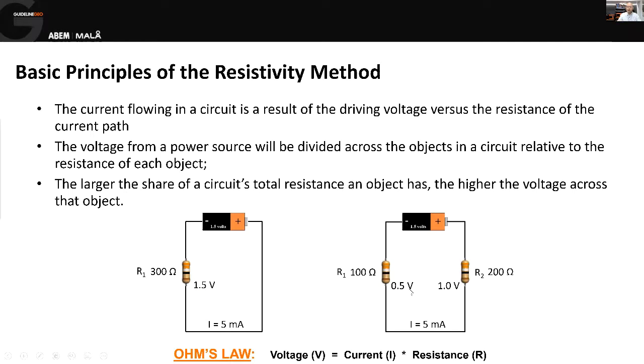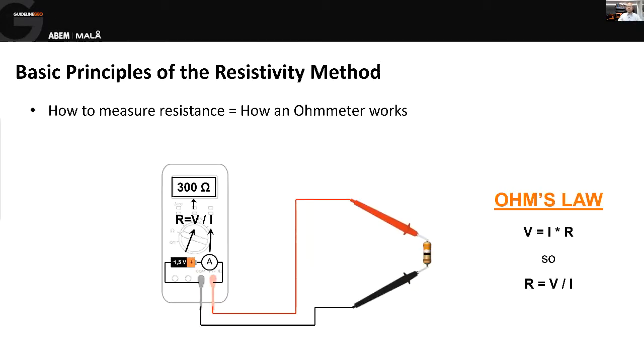So when we're talking about surveying in the real world, what we're talking about is measuring voltage at different locations on the ground, and then being able to determine the resistance of the volume of earth that we've just measured. Now, in a laboratory, doing those measurements is really easy. We can just use a simple electrical test meter with two probes. We put the probes on either side of the component that we're interested in, and Ohm's law will give us our resistance by knowing the voltage in the battery and the current flowing through the circuit.